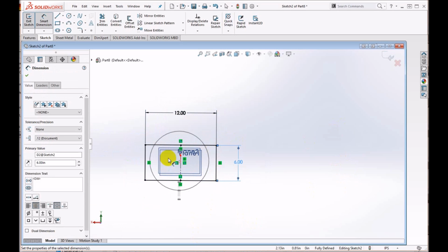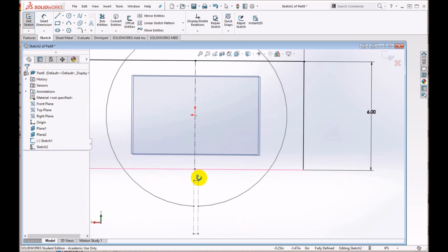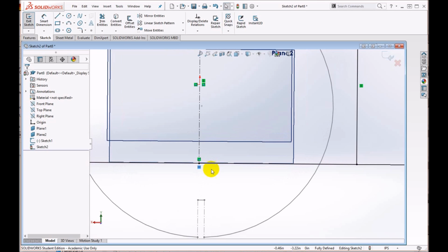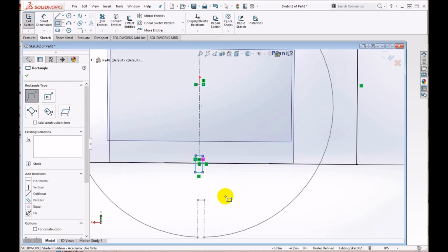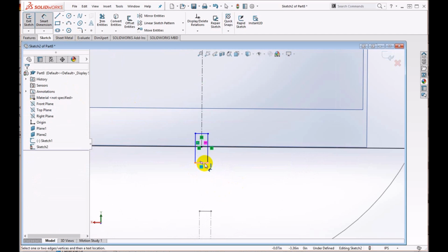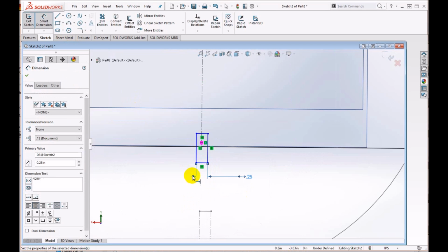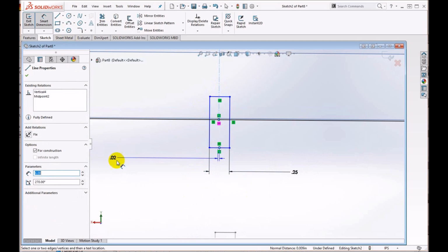So last but not least, just like I did with the circle, I have to create a notch in the bottom center, and so let's make that. I'll create a little rectangle, put it on there, make it 1/4 inch wide. Let's make it coincident with this line.